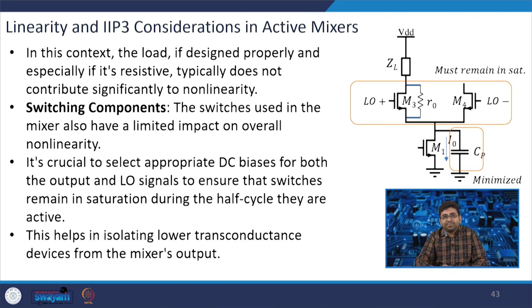And linearity and IP3 of the active mixer. So, as I told, it is proportional to overdrive voltage. In this context, the load channel, if designed properly and especially if it is resistive, typically does not contribute significantly to nonlinearity.